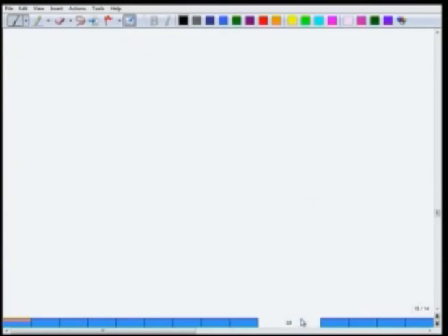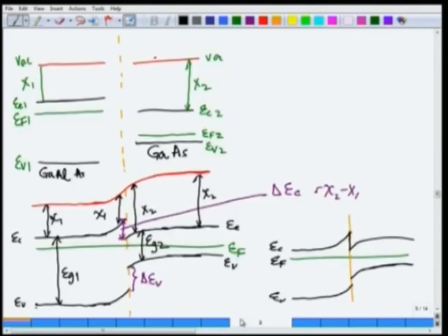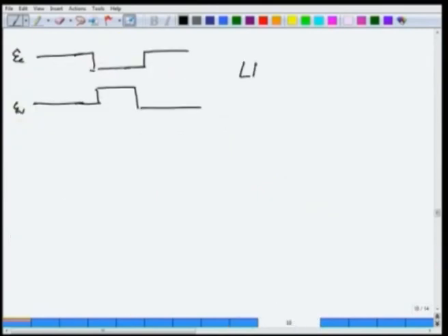Also, in LEDs, you will have to take a semiconductor which is like this, another semiconductor in the middle, and then another semiconductor which has a bigger band gap. You take three semiconductors like this and make LEDs. This will be Ec and this is Ev before joining. When you join, this nature will change, as you have seen. This is what I was trying to teach you, how this junction area changes in behavior. When you join them like this, they change to this behavior. The same thing will happen here, and you will use this in LEDs, and hence these types of diagrams are very important.